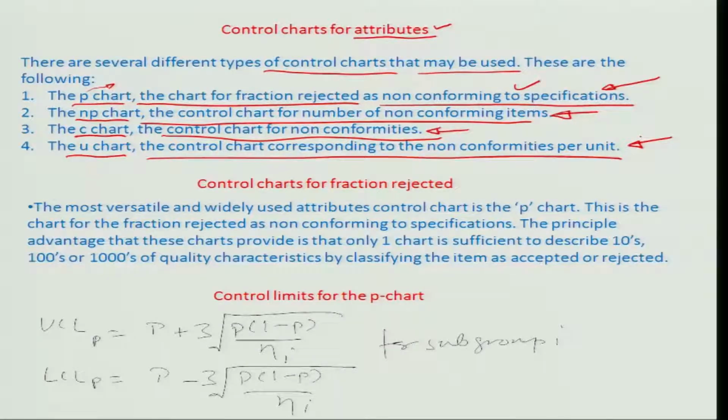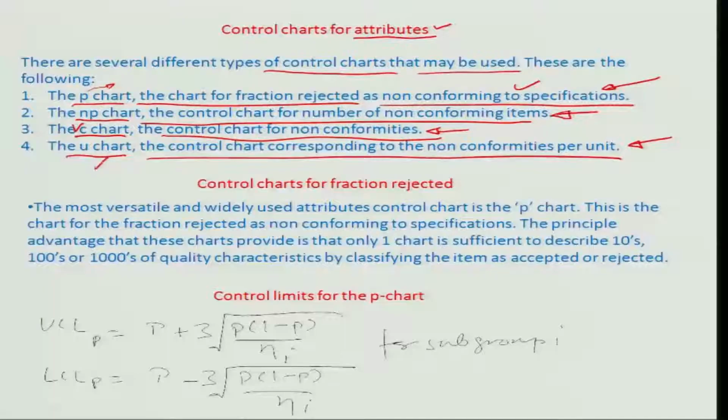Okay. So, the C chart is sort of an occurrence of a non-conformity, but in a non-conforming piece you can have many specifications which run out, so more than one specification sometimes creates a problem. You have two or more defects within the same non-conforming piece you are examining in acceptance sampling. So, the U chart keeps track of the number of non-conformities per unit, vis-a-vis the C chart, which talks about the number of non-conformances in a production line.